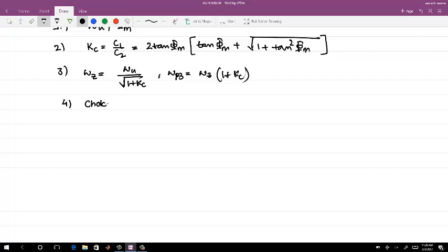Let's say I start by going with a very stable system, 88-degree phase margin. But for 88 degrees you may end up with a capacitor of 1 nanofarad. Can you have that 1 nanofarad capacitor? So then you say, okay, I will go for 70-degree phase margin, and you will have a capacitor of 100 picofarad. The question is, can you still give that area for 100 picofarad? Those trade-offs will come in the design process. If you follow this process, all the variation of the parameters is before you, and then you just make the choice.